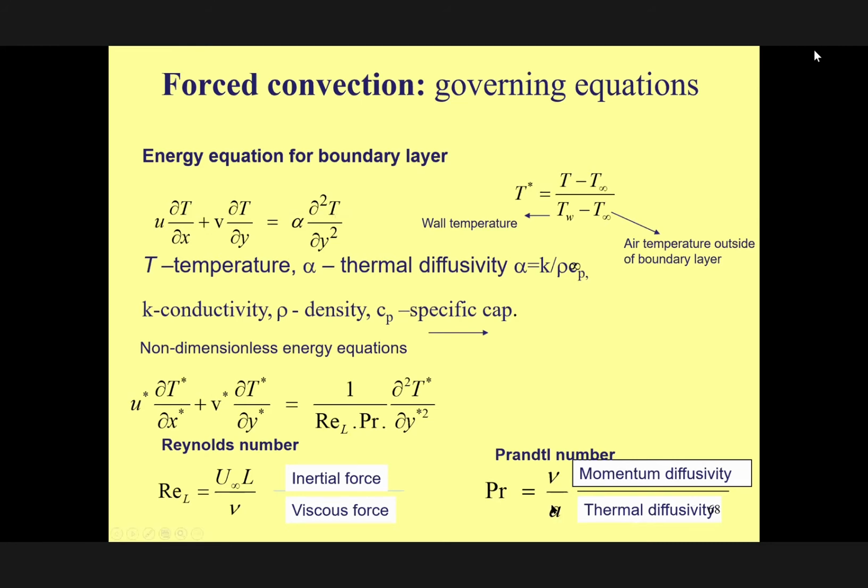And here we have alpha, which we call thermal diffusivity. If you look at its definition, we have Cp and K, which represent the effect of Cp and K. Therefore, this represents the ratio of two types of motion: motion by momentum inside the fluid, and motion by energy, by conductivity. That represents which one is dominating. In the case of a liquid metal, a material with very high conductivity, you expect the Prandtl number to be low. Okay, thank you, sir.